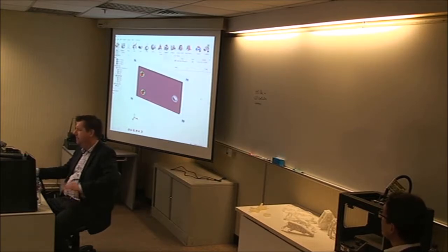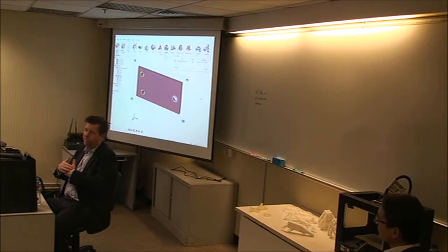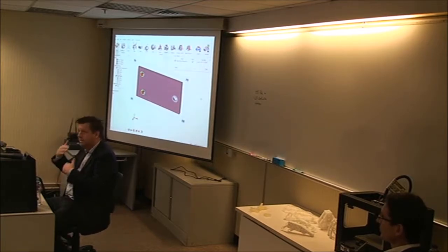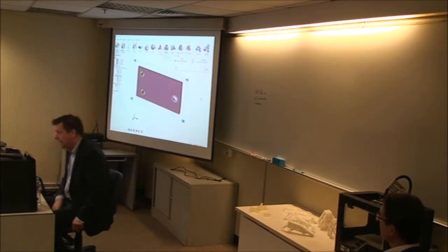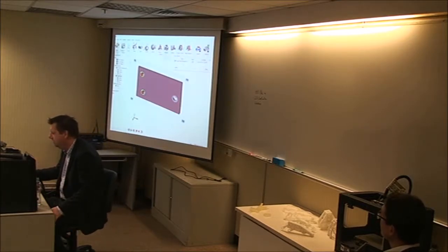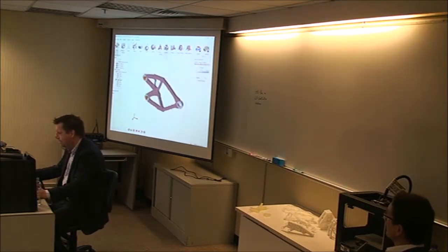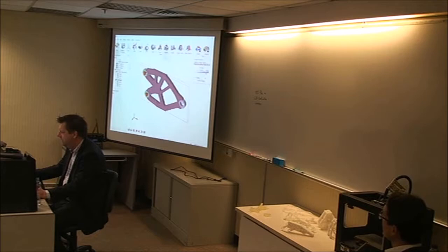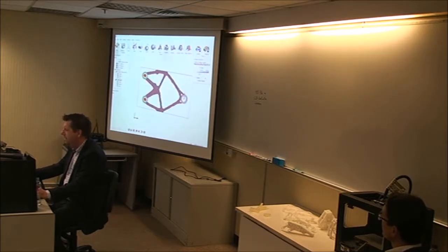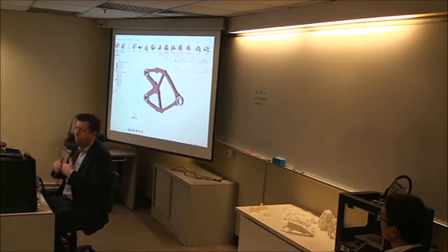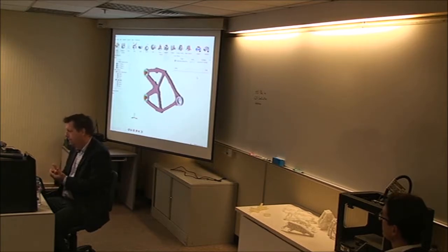So that's run. Again, the optimization is an iterative process, so it probably ran 20 to 40 iterations. So it's total solves each time. So again, it's pretty efficient. So I double click on that result. So there is the topology result. As I mentioned, you could look at the different thresholds, way up here, way down there. I can do an analysis on that. So again, in the background, building a mesh based on that, and we'll run it.